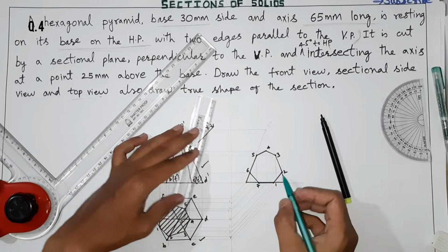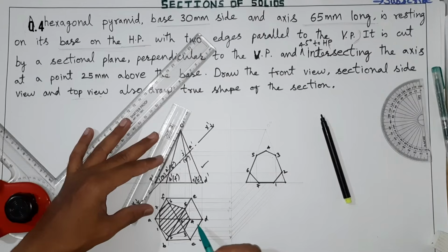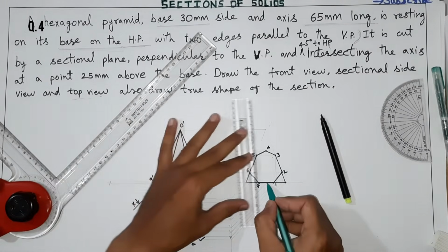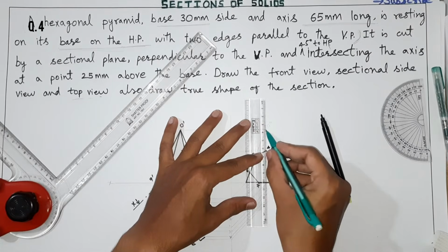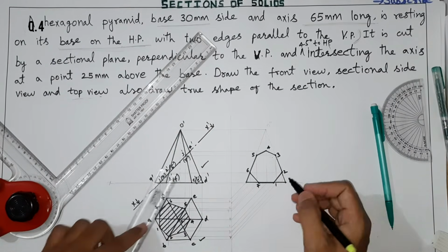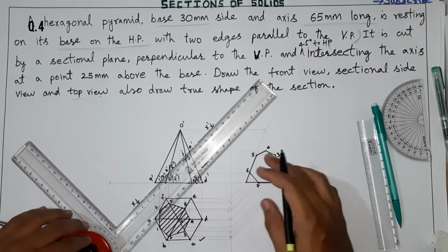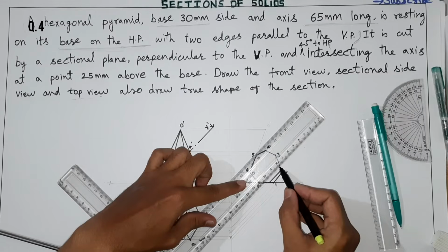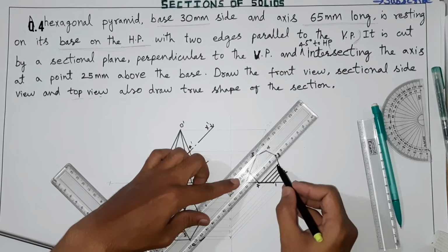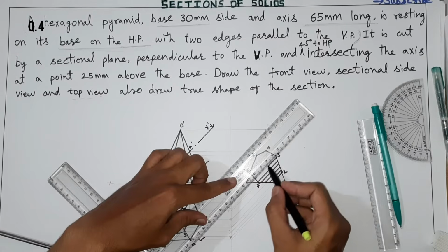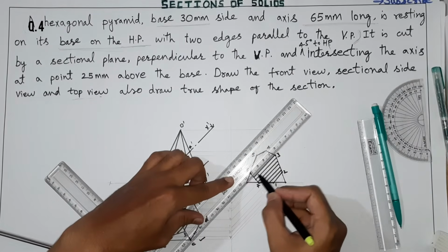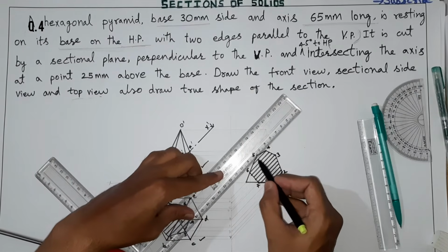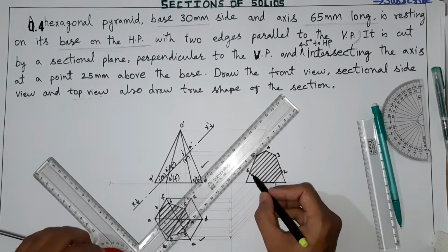And from points where the D point is here, center point, here you can draw thin line like this. Already thin line is there. Just further, now inside this section we have to do hatching. 45 degree line. Hatching lines are 45 degree lines equally spaced. We will use hatching line to show the section area. Section area is what? After cutting, whatever new surface is coming, that's called section surface or sectioned area.